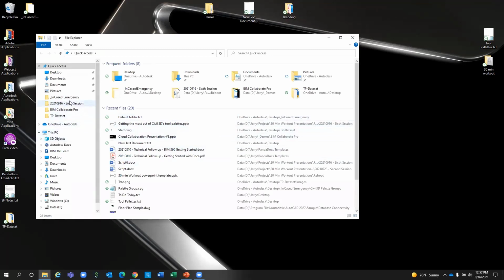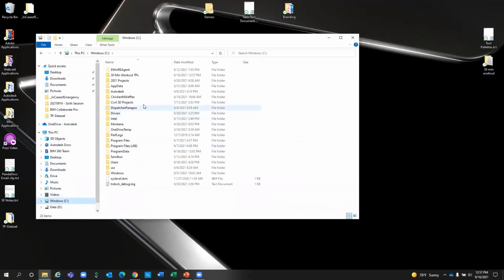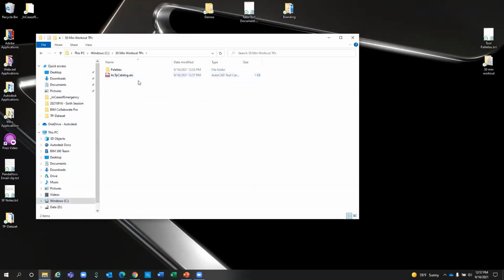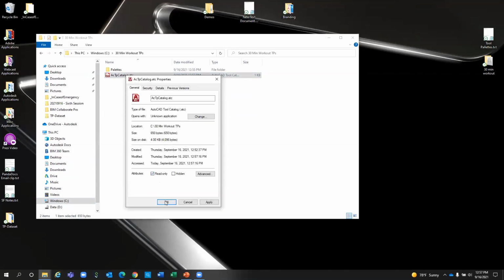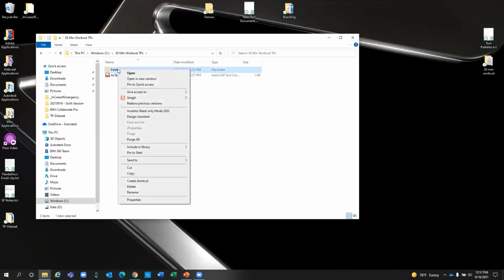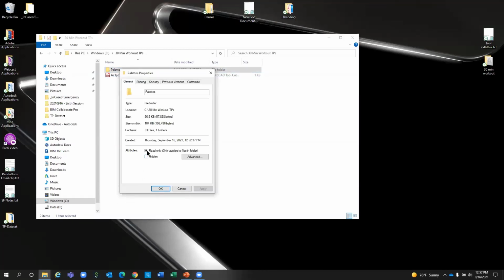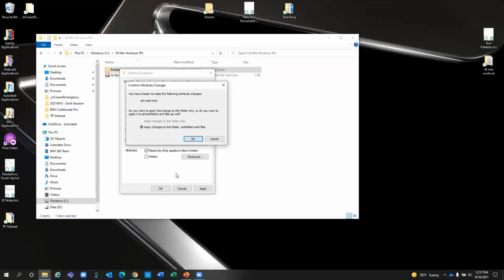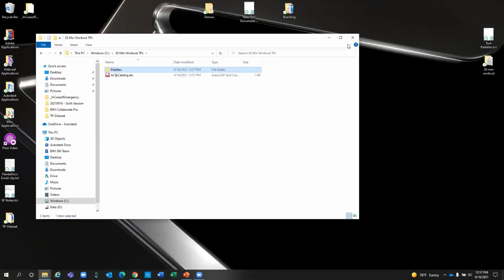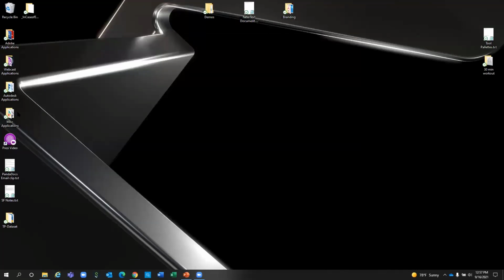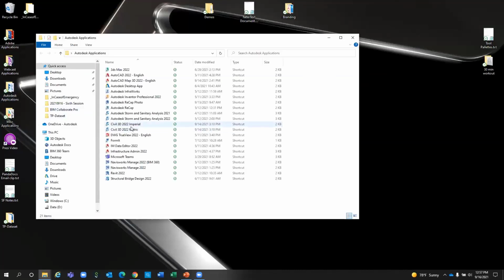I'm going to come to that folder. So we'll say C, we'll go to 30-minute workout tool palettes. I'm going to go to properties, and I'm going to set that catalog to read only. I'm going to go to palettes, go to properties, and set that all to read only. We'll say okay. That is good to go. Let's fire up Civil 3D one more time.